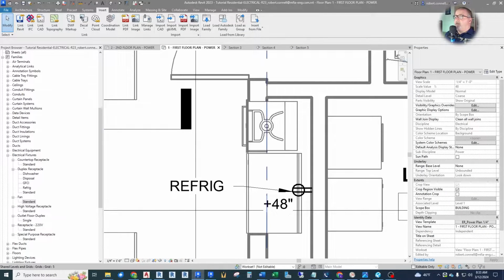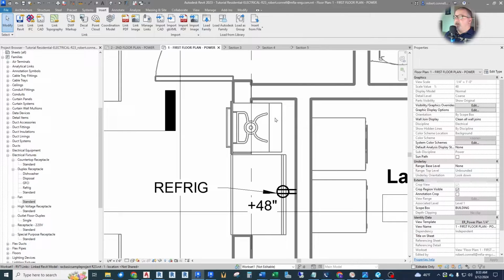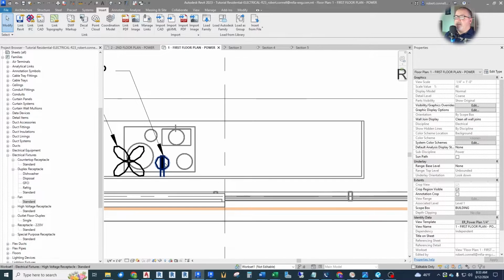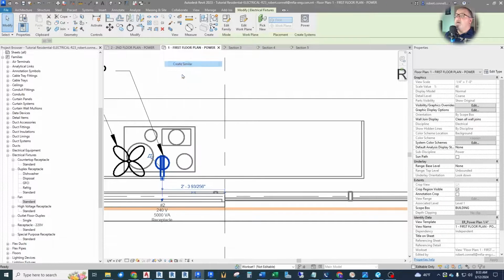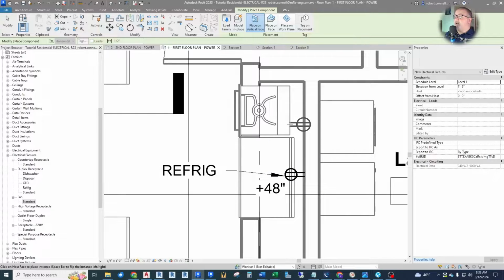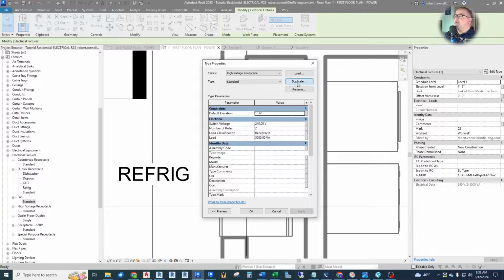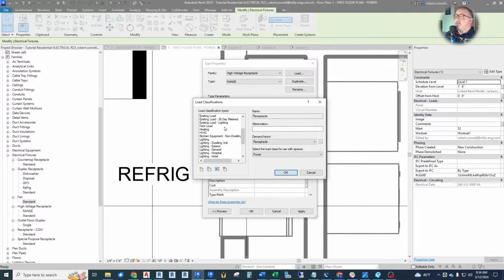And then up here, these are one standard and one special. Our range is going to be this guy, the 240 volt outlet. So let's get that in there. Let's go here and call this range. We're going to make that more like a 9,000 VA. And we can call this electric range 3.5 to 8. We're close to 875. We can leave that there.